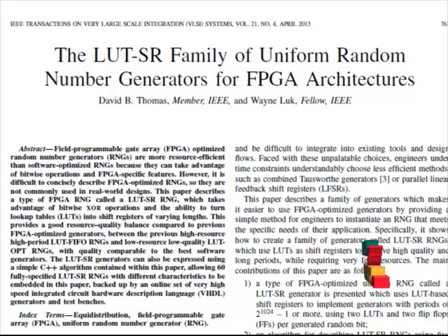In particular, uniform random bits are extremely cheap to generate in an FPGA, as large numbers of bits can be generated per cycle at high clock rates using lookup tables or FIFOs. In addition, these generators can be customized to meet the exact requirements of the applications, both in terms of the number of bits required per cycle and the FPGA architecture of the target platform.